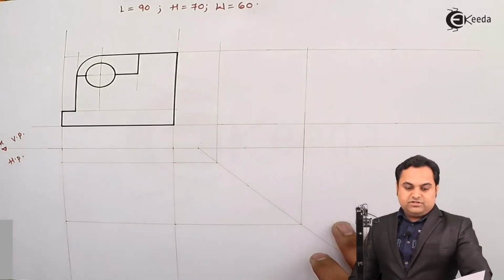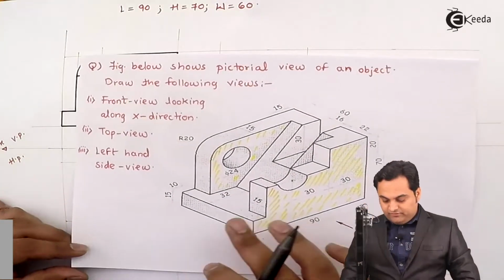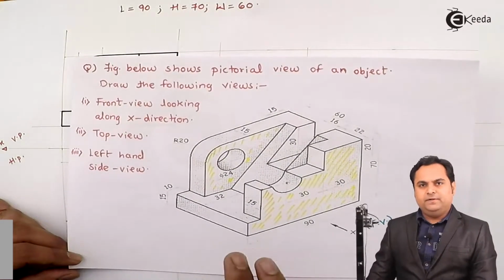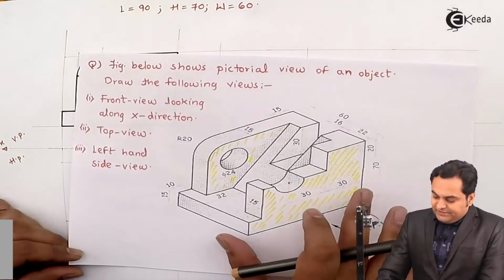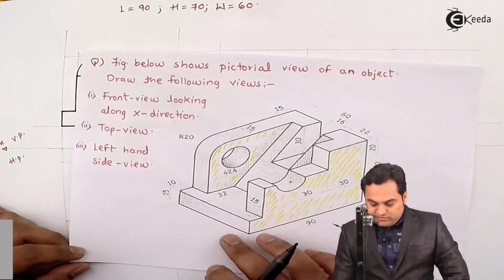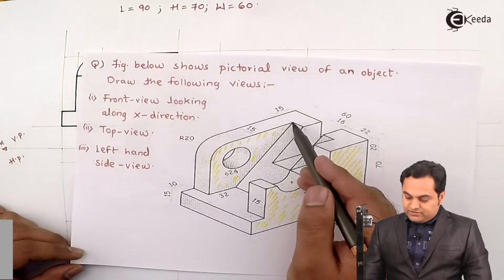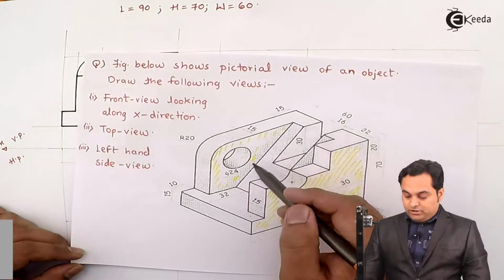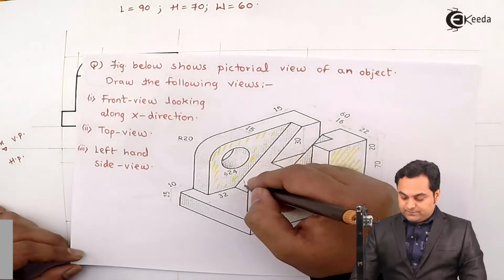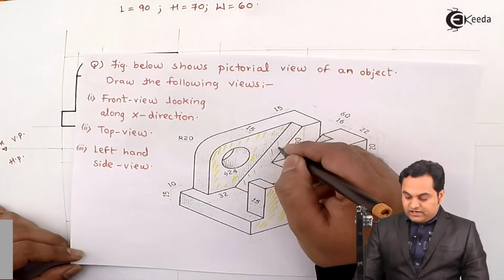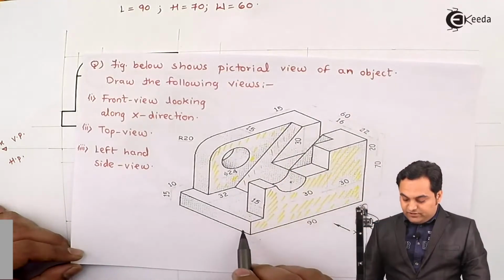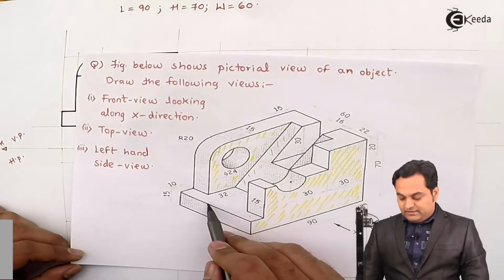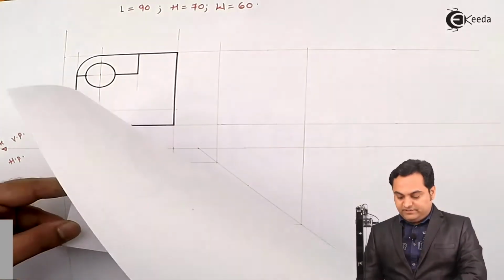Now this much is the visible portion in the front view. The remaining things whichever are there inside, those are the hidden details. So at first, there is this slope which would be hidden, and where it is connected, the sloping surface is starting after this 15 mm block, and then it is at a length of 32 mm from the left hand side.